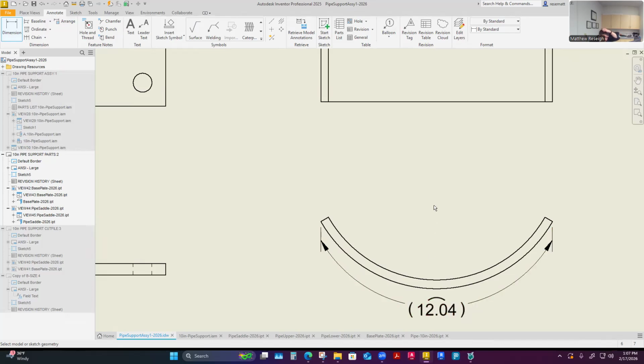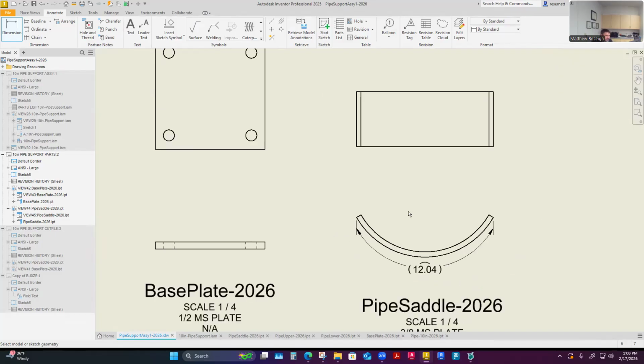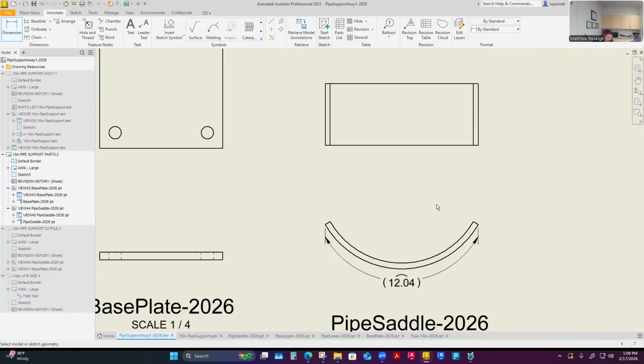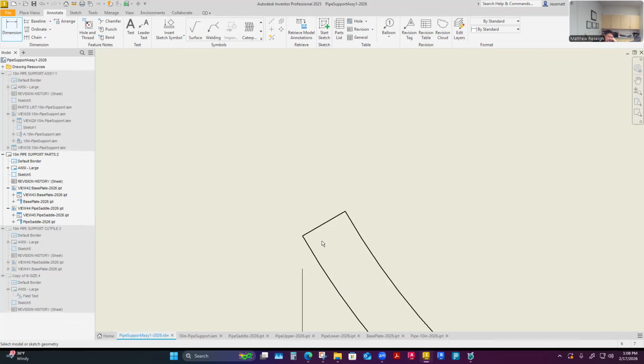So this is just a reference dimension that, once I get it formed and I've pulled it, I can wrap a tape around the outside, which would be quite easy to do. To wrap a tape on the inside is kind of weird. I mean, they have flexible tapes like a fabric tape measure, but really just rolling a tape measure around the outside, I could quickly identify this part, because sometimes your prints are just used for part identification. If this has been formed, it doesn't measure what it did flat anymore. So if I have a pile of these, and they're not etched or something, how do I recognize them? Well, I have a few dimensions here to help you.